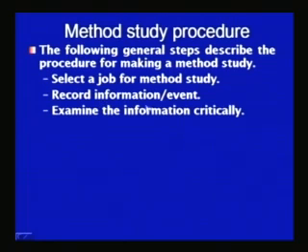The recorded information is examined critically to see what are the relevant and important elements of the job, and what are the unproductive activities or parts of the job, so that the methodology for carrying out the job can be improved by either simplifying, by combining some of the steps of the methodology, or by eliminating some of the steps which are not required.